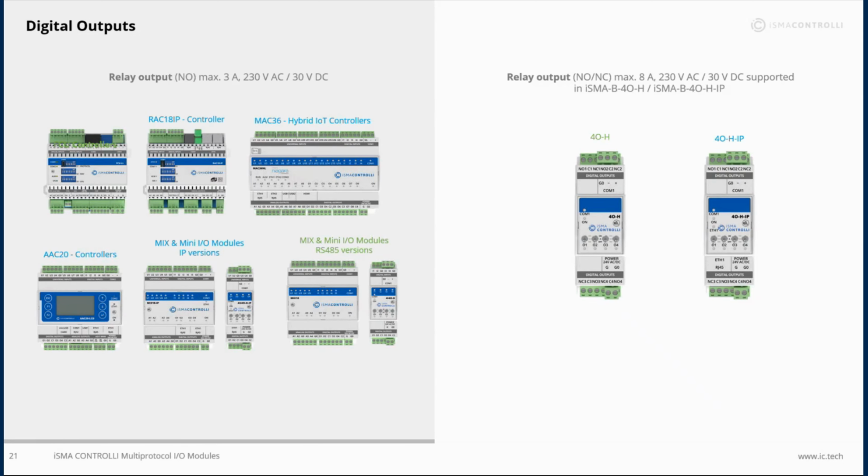And then our digital outputs. All of the digital outputs in the product portfolio are relay outputs, and you have an option of standard 3 ampere relays, or you can select for lighting applications larger 8 ampere relays available in our 4.0 mini modules.